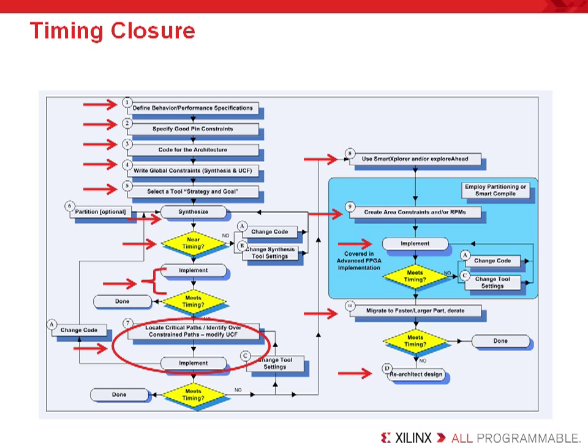To do that, you first have to choose an appropriate device family that can meet your performance needs. And we're going to talk about what kind of performance you can expect from your device and how to determine that. The next topic is planning a good design pinout. This will directly affect your input and output delays, so it's important you follow some good guidelines, and we'll try and talk about a little bit of those when we get up to it. But in general, you're planning your pinout to be placed for your board level needs, but also trying to place it to meet your internal needs of timing inside the FPGA, so it's going to be placed near your logic. HDL coding is perhaps the most important topic, and as you can see, it comes very early in the design process.